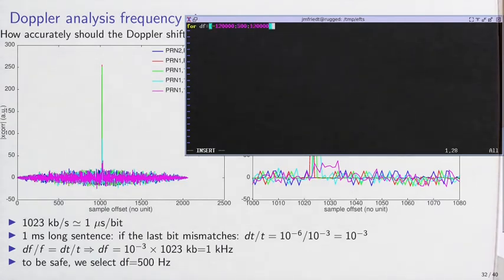And what we need now is to create the frequency offset. So we take, say, only the samples from D from 1 to the first 100,000 data. And so we create time. Time is the sequence from 0 to length of D minus 1, and this is divided by Fs, the sampling frequency, of 2 megahertz.